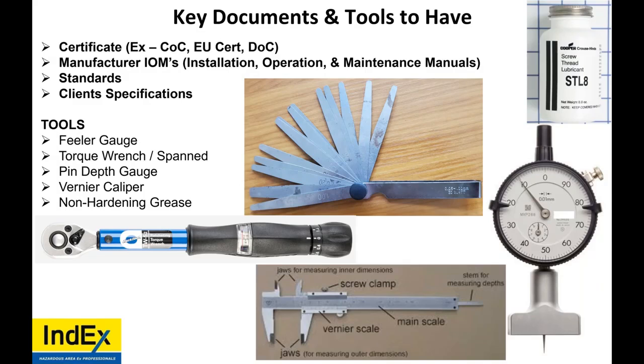If we drill a cable gland hole in an explosion proof JB on site, is certification required? Flameproof, you cannot drill a flameproof enclosure, okay? You in the field, you on site, you cannot drill it. You are not allowed. The certification and the safety of it are completely compromised. Do not do that. Please, do not do that.